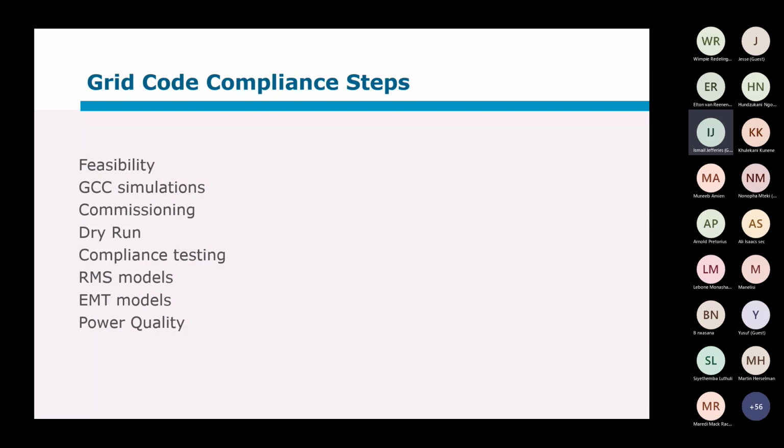And then on the greater than 1 MVA, the requirement becomes even more stringent. It's definitely required there. No debates, and they would need to provide a protected substation building to be able to facilitate that in terms of the SCADA, because that's the easiest way to facilitate it, and not with, for example, your old outdoor ring main units.